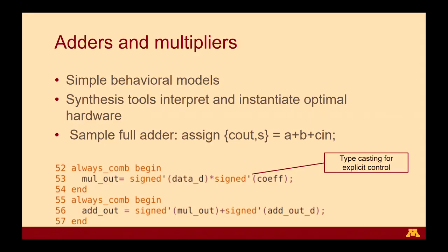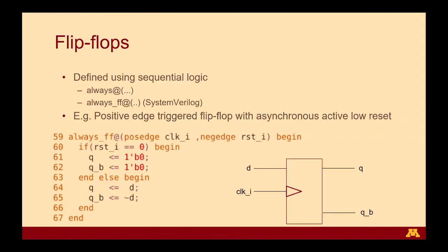In this scenario, you would take the multiplier to the full precision that it allows for, and then in another line of code select the bits you require to keep. For example, in the 16-bit output, if you do not require all 16 bits and want to truncate it back to 8 bits, you can do that in the next line. For signed numbers especially, it's important to keep note of sign extensions. In SystemVerilog, they have the facility to do sign extensions with typecasting, which was not there previously in Verilog. You should make use of this, especially if you're doing any signed operations.